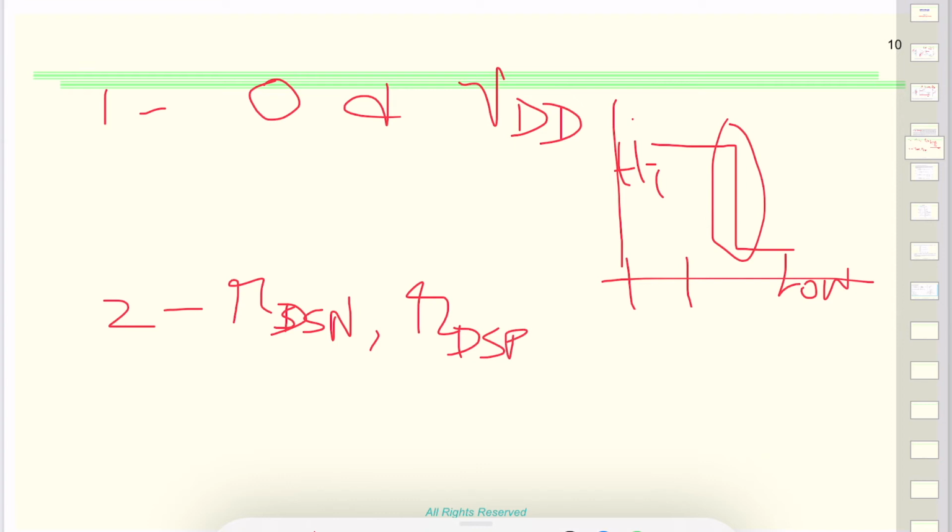So we could find those resistances, but we just ignore that. We ignore the leakage currents also, for the simple reason that there is no DC path between the power supply and ground in either high input or low input. The third observation is there is a very low resistance path between the output terminal and ground. So that's three. Number two is zero power dissipation.